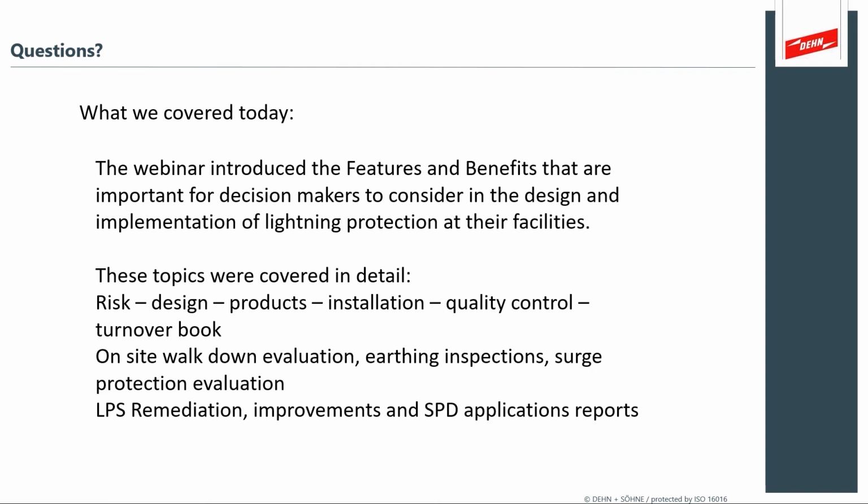As for the ideal reading, that's somewhat of a customer requirement. For instance, we have customers that mandate less than 1 ohm for the earthing system, so it's possible to use that type of meter to evaluate each node.